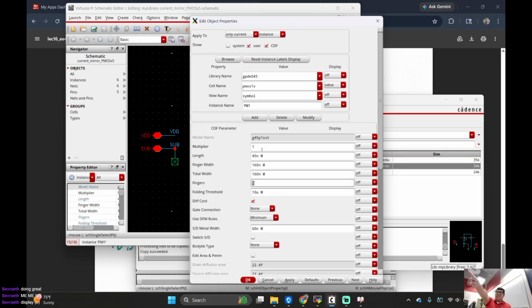But you as the engineer, instead of 10W, right? Big long MOSFET, right? Why don't I just chop it into 10 pieces and just make 10 fingers? Personally, that's much smarter to do. But I, as the PhD designer, said, no, just try this. So Pegasus may tell you that the designer of the circuit wants you to do it like this, Mr. Layout Designer. I think I know what you're talking about.